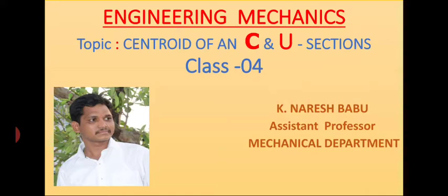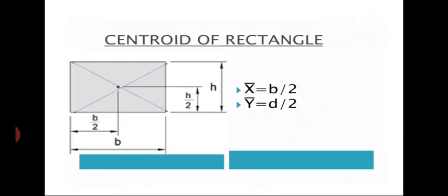In this class, I am going to explain about the centroid of C and U sections. This is my fourth class. First of all, you have to know the centroid of a rectangle. The centroid of a rectangle lies at half of the base and half of the height.